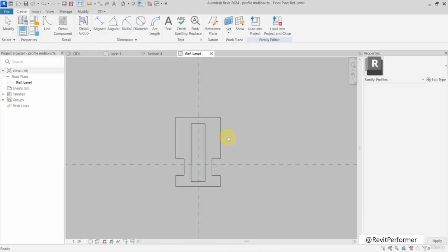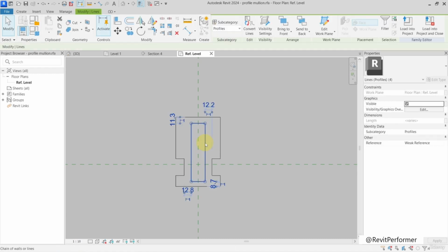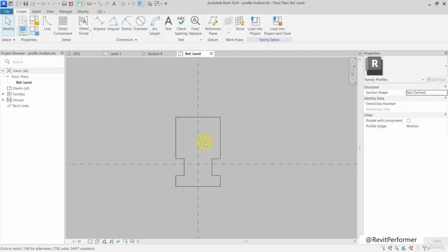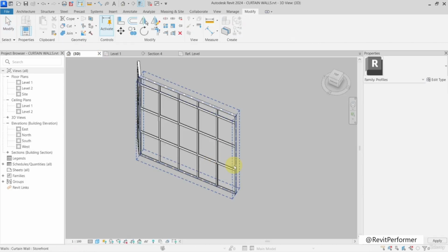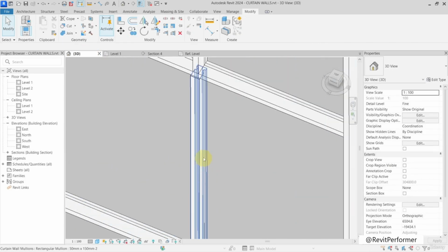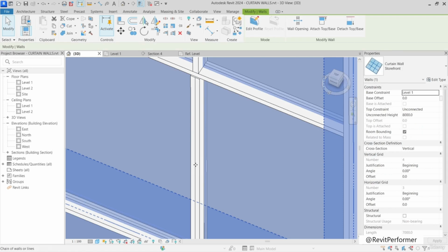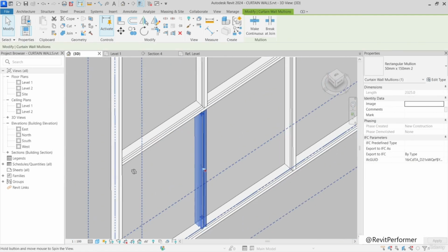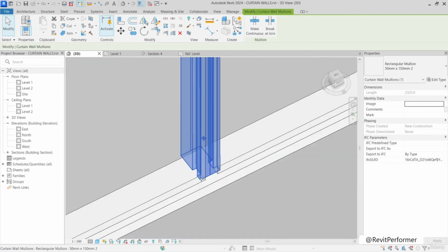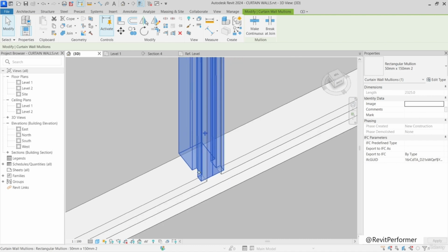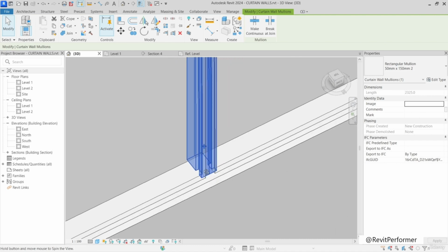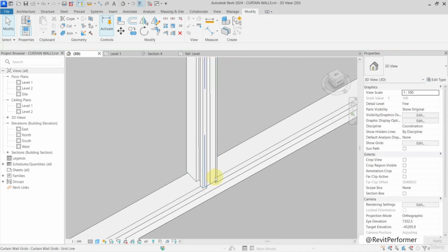So I can actually model it more. Me personally, I try not to over-model things, because then it is more and more. If I would model this even more detailed, there are more things for Revit to show me graphically and to talk with, and it will slow down Revit. So it's always: do I really need it or not?